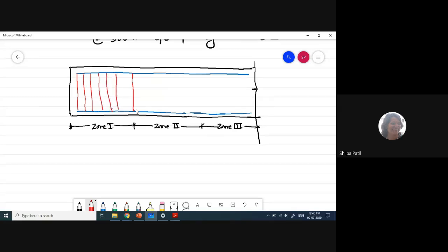Please make use of scale when you draw the diagrams. Now, using a tablet, it is difficult to use a scale here. So for this zone, I am providing 10 mm diameter, two-legged at, what is the spacing? It is 100 center to center. Am I right? Yes, ma'am.